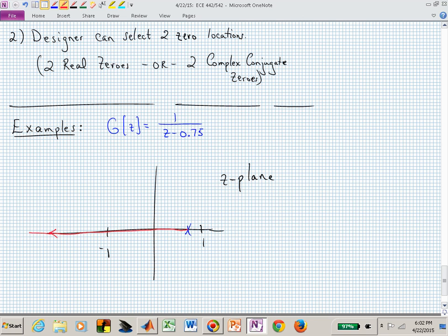Steady state accuracy. You're going to have some error between where you tell the system to go and where it actually goes. With just a gain controller, you do not have what? You do not have a pole at z equal 1 to give you zero error due to a constant input. If we now introduce a PI controller, we could simply say that K is something over z minus 1.